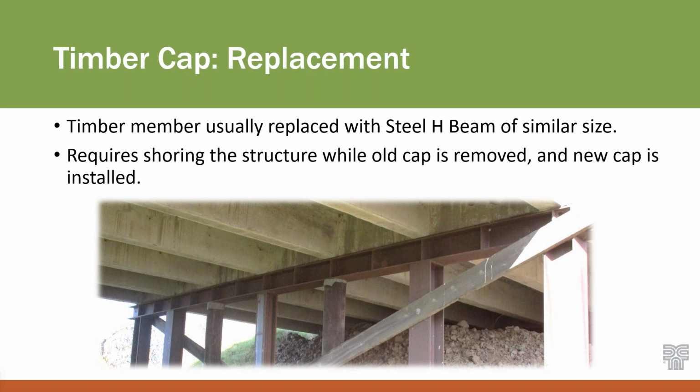And of course, you could just rip the cap out, right? You don't have to keep the cap in service. You can take the timber cap out and replace it completely. You can put in a new timber cap, or you can put in a steel cap. Steel caps I seem to think are more prevalent.